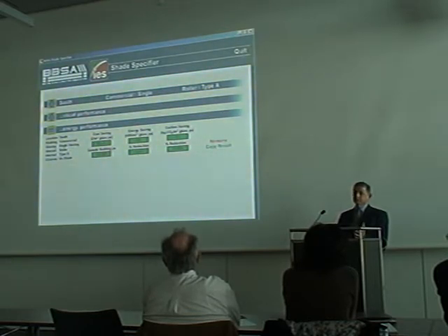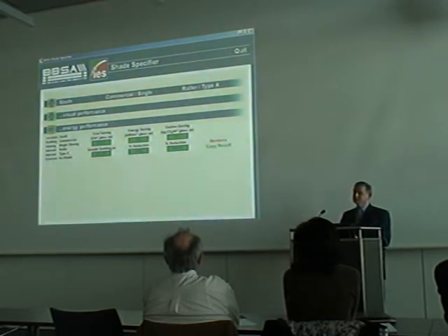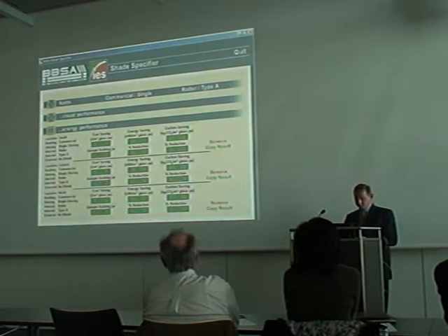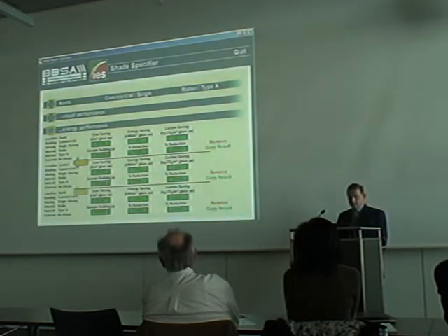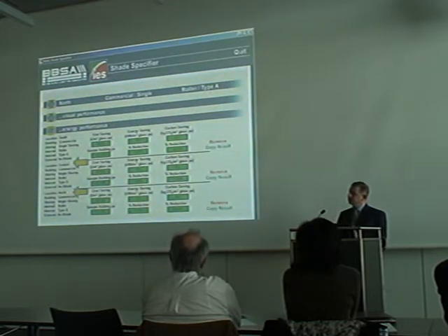And the reason the two aren't the same is because air conditioning tends to use electricity. Electricity tends to produce more CO2 than gas, of course. So we can see in that sample building that we're saving around about €2.11 per metre squared. If I run the same analysis now for the centre of the country and the north of the country, it's exactly the same analysis, just moving the weather data.